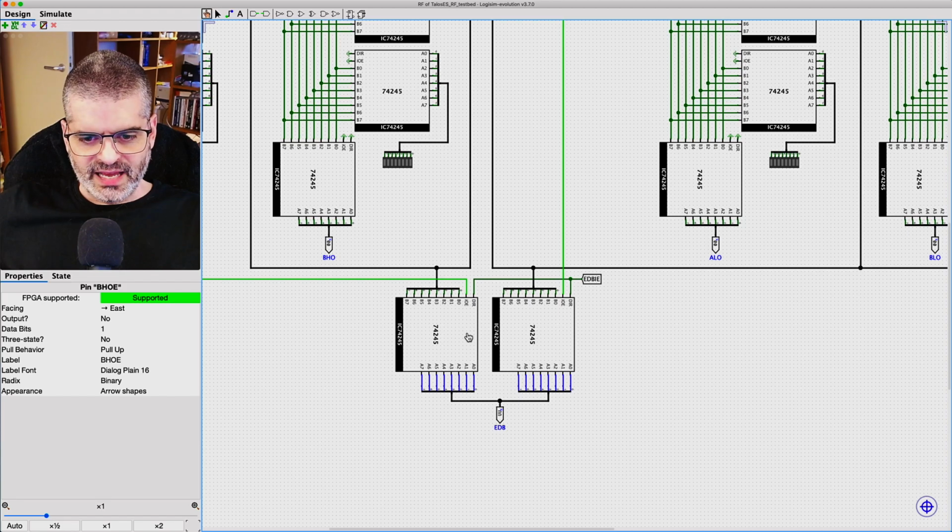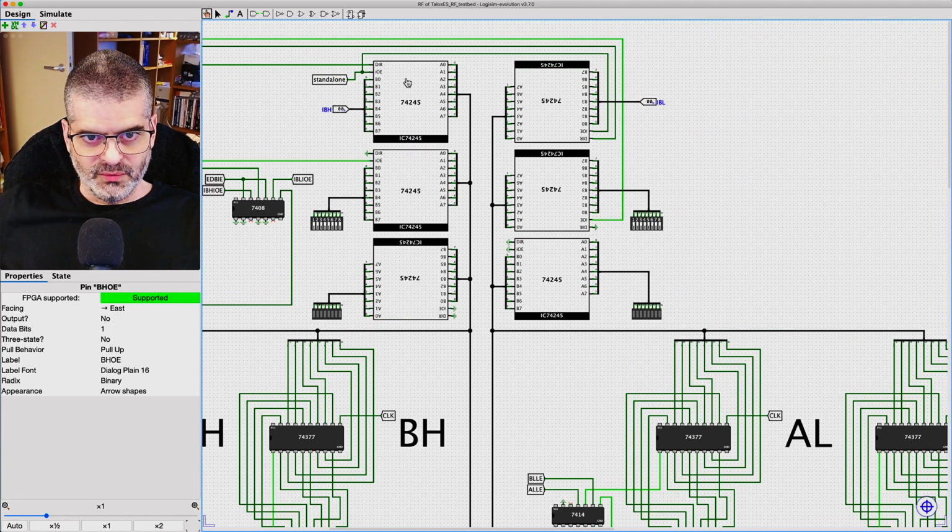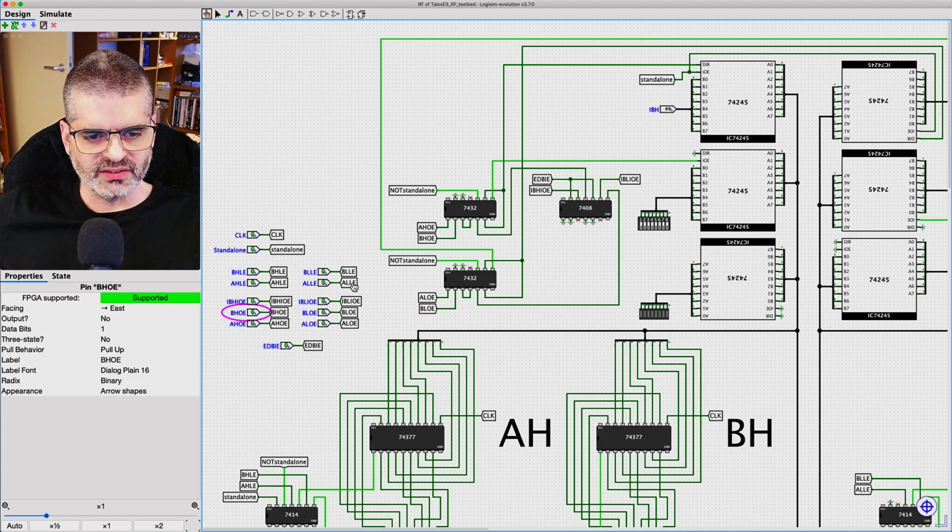And once that happens, then we'll be driving a value into the high byte of the bus, and now this has to become an output driver. So the direction here has to change. Let's see if it will change. If we just say internal bus high IO enable, now we know it's an IO, but it may be an output, so we don't need to change the direction. But the moment we go to external data bus input enable, now the external data bus should be driving the high byte of the local bus.